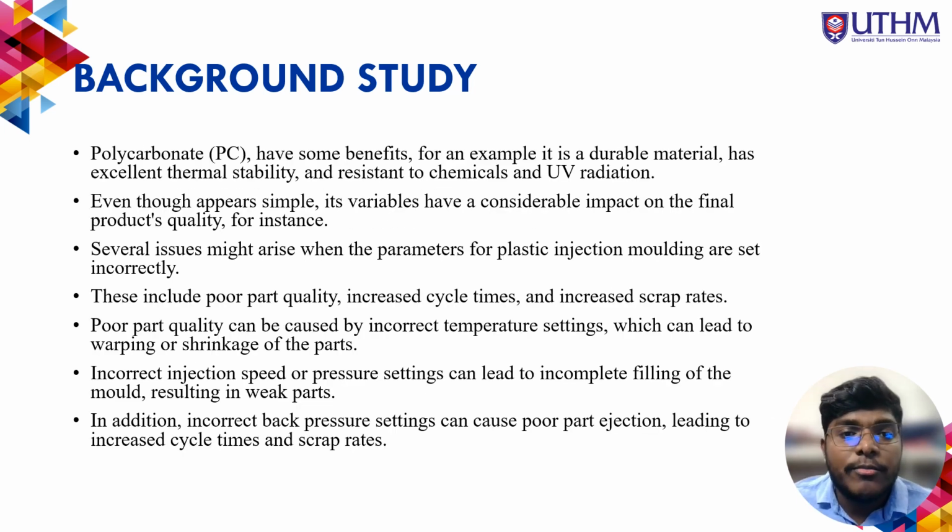The continuation of the background study. Plastic injection molding resin such as polycarbonate has some benefits. For example, it is a durable material, has excellent thermal stability and is resistant to chemicals and UV radiation. Even though plastic injection molding appears simple, its variables have a considerable impact on the final product's quality. For instance, several issues might arise when the parameters are set incorrectly. This includes poor part quality, increased cycle times, and increased scrap rates.